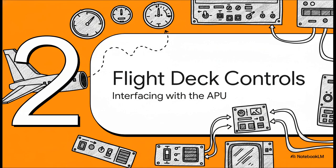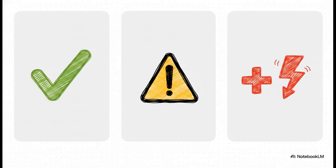Flight Deck Controls. How we interface with the APU. The primary way you interact with this system is via the APU control panel up on the overhead console. But you visually monitor its status on the multifunction display, or MFD, specifically on the electrical page. And this page brilliantly shows the visual logic Bombardier uses to talk to the flight crew. In normal states, you'll see white digits. Or when it comes to generator load, if the load is exactly in the expected range, nothing is displayed at all. Basically, no news is good news.